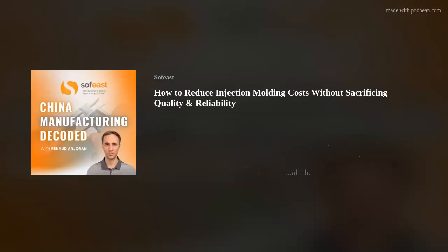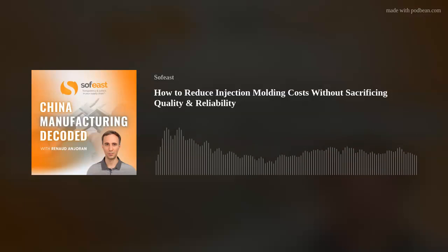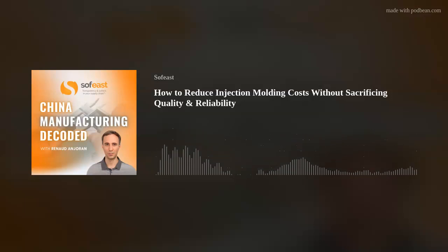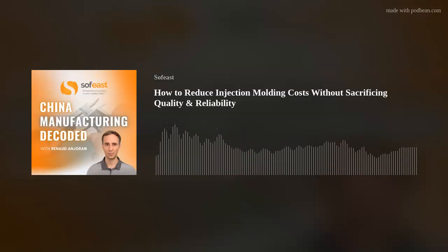This is insane. Well, it's because it is insane, because of the tight tolerances are specified on areas that don't need to be. In other words, if you are looking at machining and then grinding and then hand polishing in order to get to that 0.05 millimeter tolerance, when it doesn't need to be, you've added so much time and effort, i.e. additional money, in order to achieve something that is not necessary. Okay, so that's the first part, overkill on tolerances.